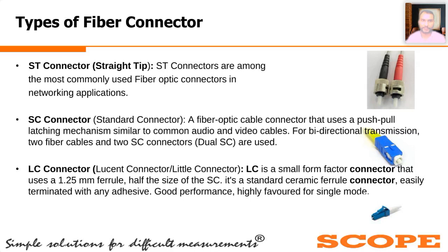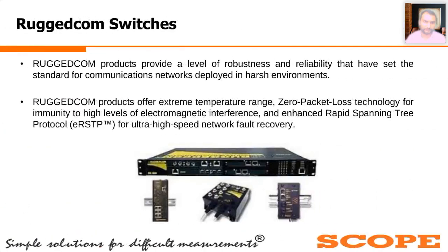Based on application, you can use them. Normally, ST connectors are more popular because of simple use. You can go for LC connector if you are using small form factor SFP switches. Then you have to go with LC connector. So based on your application, you can choose the connectors.